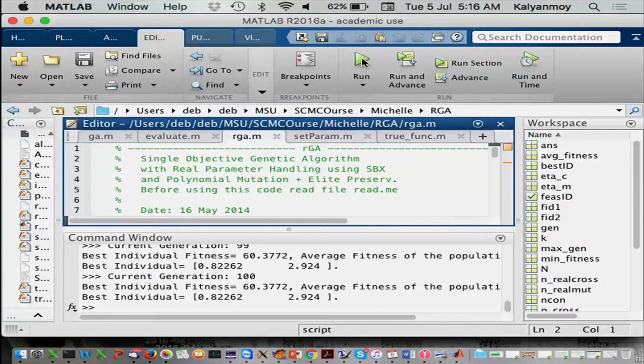But it still needs that R. You still may be wrong. 1 million still may be less for another problem. Okay, so then you have to try one more time, increasing it to a higher value and see what happens. But the penalty parameterless approach, which I showed you before this, I didn't even ask you any penalty parameter, and we still get the same result, which means it doesn't require anything. Okay, so you don't have to worry about choosing an R. So that's a bit better. So number 5 here is the best way to solve, and I would recommend you use that method instead of this penalty approach.